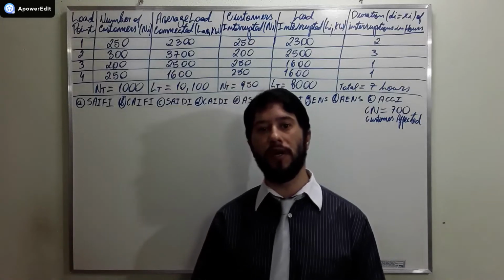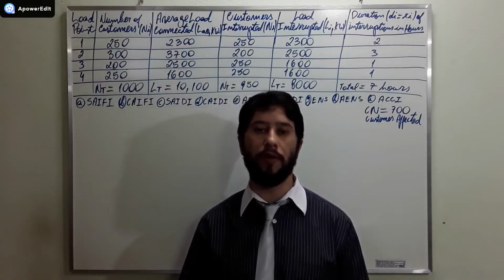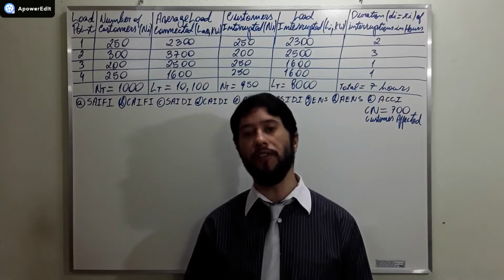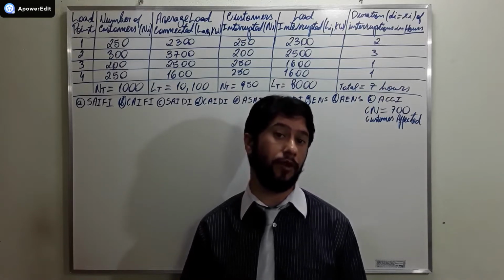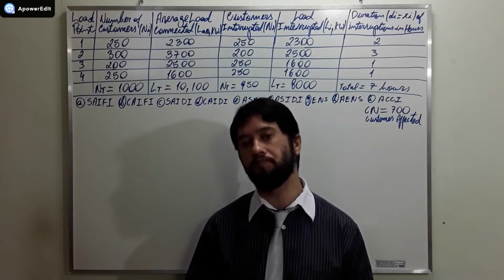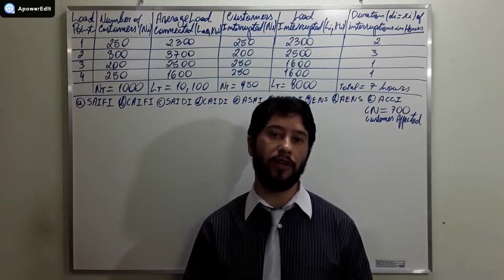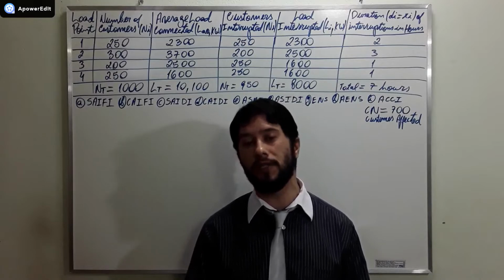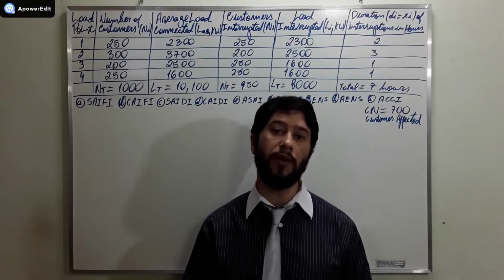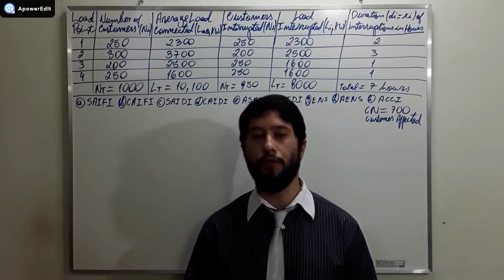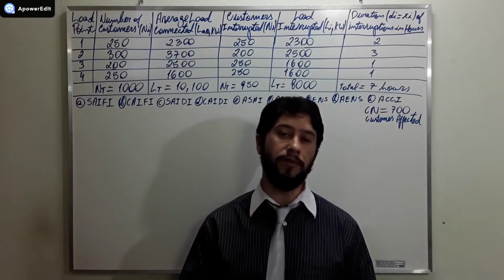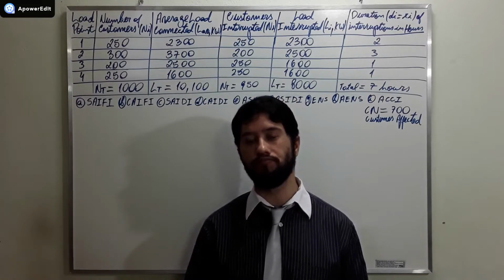The IEEE standard 1366 of 2012, electrical power distribution reliability indices. Since the typical distribution system accounts for 40% of the total cost to deliver power and 80% of customer reliability problems, distribution system design and operation is critical for the financial success of the utility company and customer satisfaction. Interruptions can be analyzed through the use of reliability indices that should concern both duration and the frequency of outage.